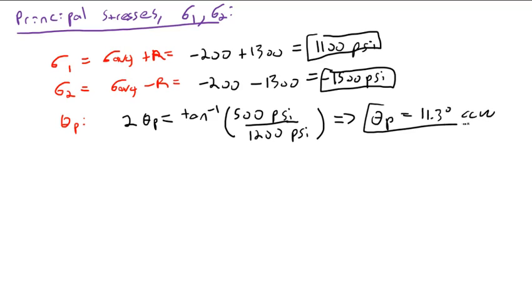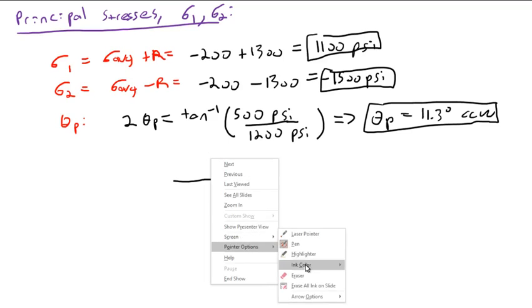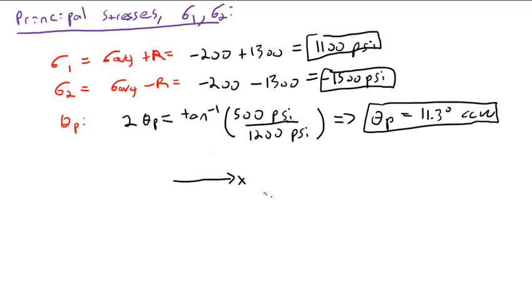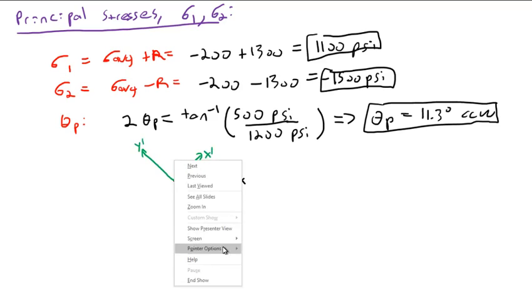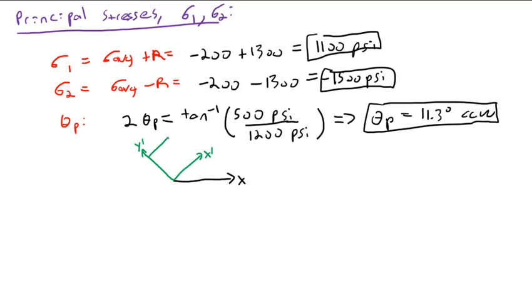And this is the actual physical angle of rotation. The Mohr circle one will be different than this. Okay. So in other words, we now have our principal stresses, our principal normal stresses, and we have an x prime. I could draw this as an x prime and a y prime, and we'd have a stress block like this.